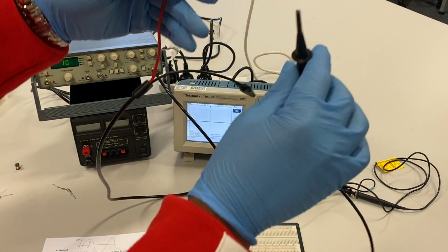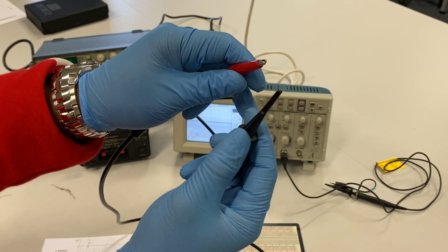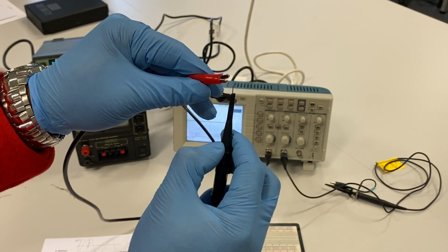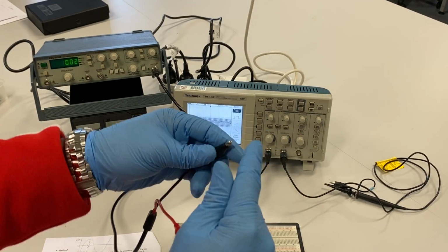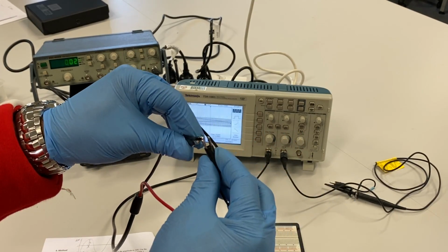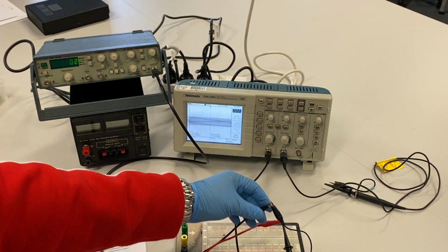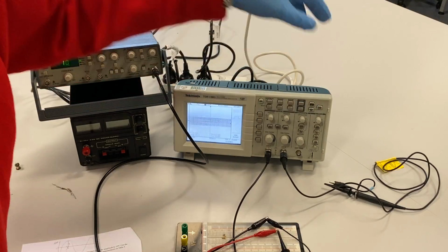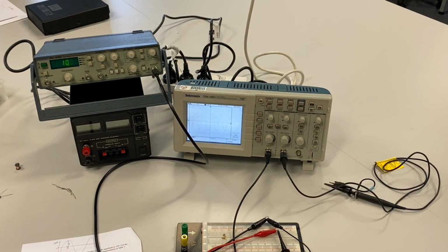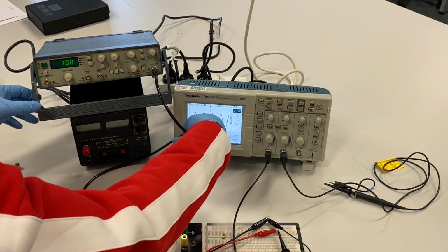So what I'll do is connect the positive of the oscilloscope with the positive output of the signal generator, then the ground of the oscilloscope probe with the ground of the BNC cable. Then I just put it like that. Like what I said, you run auto set, right? You run auto set. There we go. So we have this.